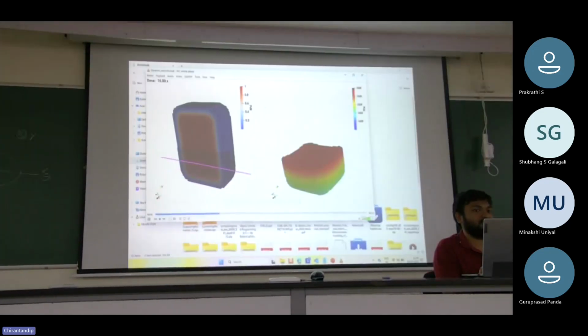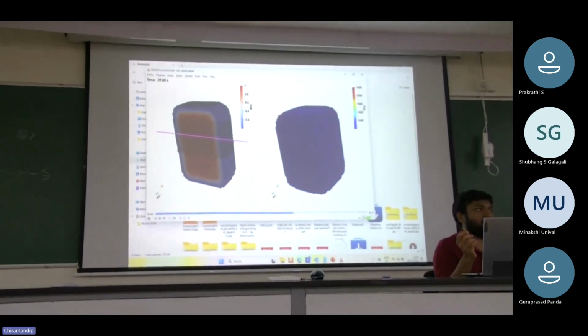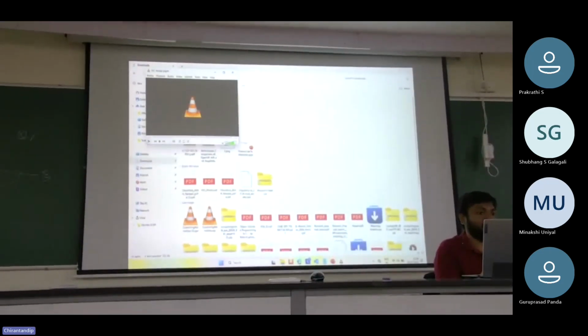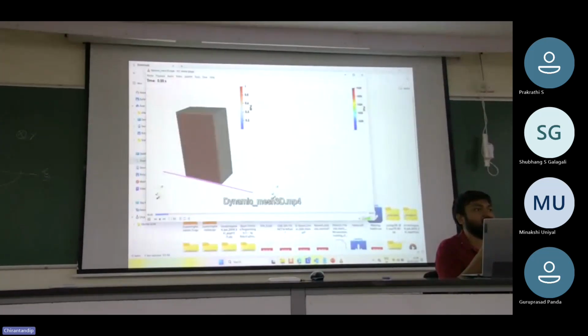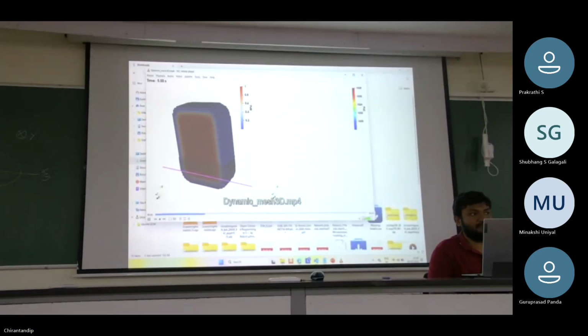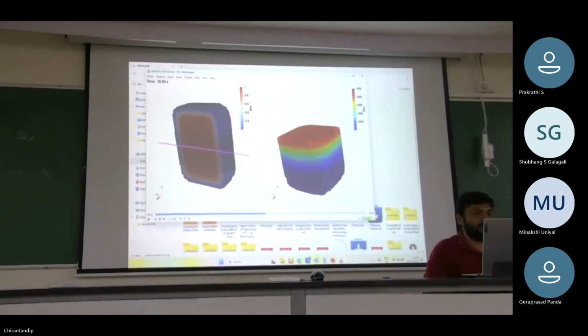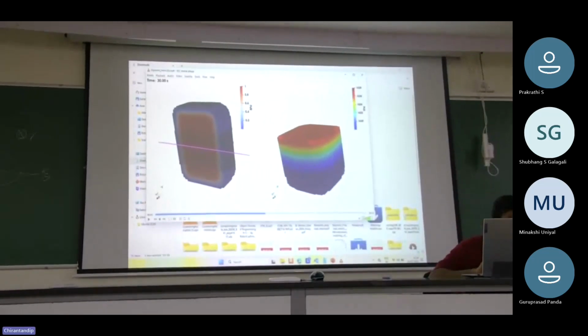There's dynamic meshing possibility in OpenFOAM, which allows you to do the same thing that we saw in AMReX yesterday. And he has done dynamic meshing with respect to the temperature field. Wherever the interface is there will be refinement. But we don't use gradients here. I directly use this. Okay. So this will be uploaded onto OpenFOAM as well. The additive module is present. Once my student's thesis is out and he's defended it, we will put it out.